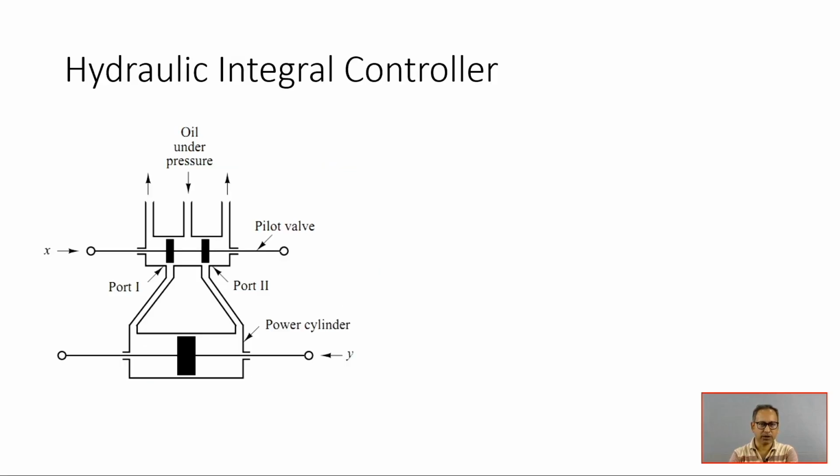Now, in this figure, this is the simplified model of this hydraulic servo system. So, you can see here this pilot valve. In this pilot valve, there are 4 ports and 2 positions. So, this pilot valve is a 4/2 direction control valve. Okay, why 4? Because there are 4 ways or 4 ports and 2 positions.